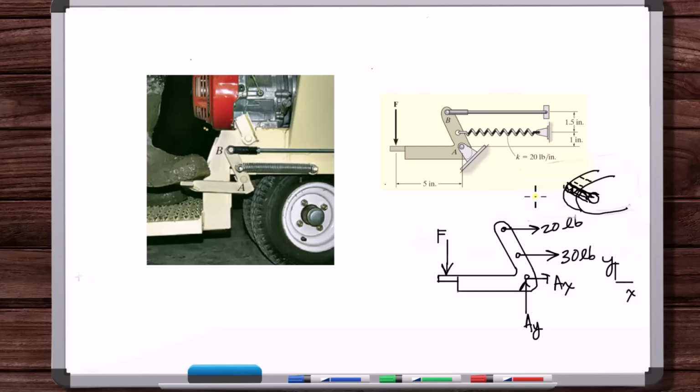In the previous section, we calculated areas under pressure curves because it was a coplanar distributed load. It was a special case where we only had to consider the area under the curve, not the volume, because the thickness was constant and it was factored into the distributed load curve. But in general, you're thinking about a volume underneath a pressure distribution. Even with coplanar distributed loads, we're in effect calculating the volume under the pressure curve. We calculate the area and the thickness is already factored in, so the volume component is already factored in.